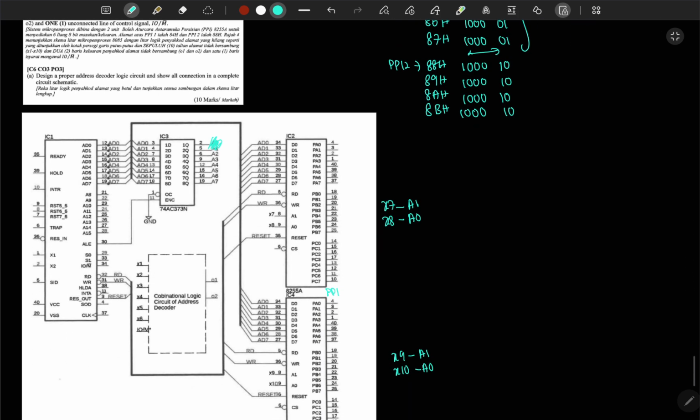Okay, the chip select is also 0. So technically, can we use other gates? Yeah, but you need to use so many logic gates. Now with an AND gate, we make everything 1, so the output would become 0. Now here the bubble means it's going through a NOT gate, so 0 going through a NOT gate should be 1.